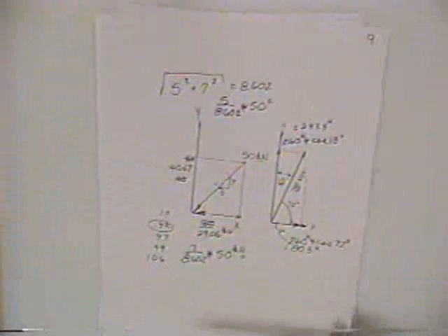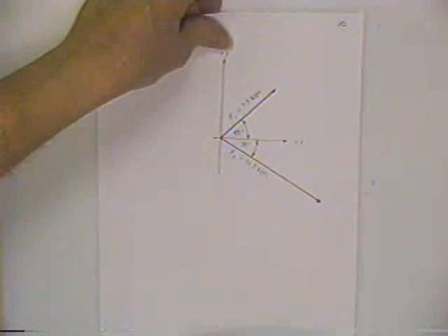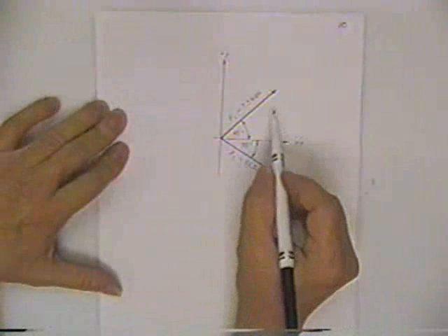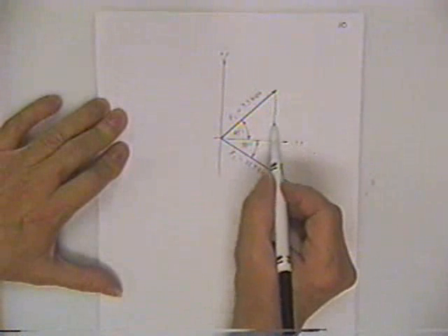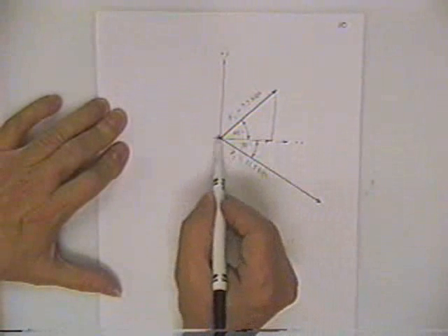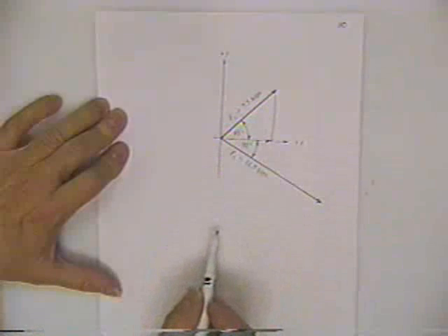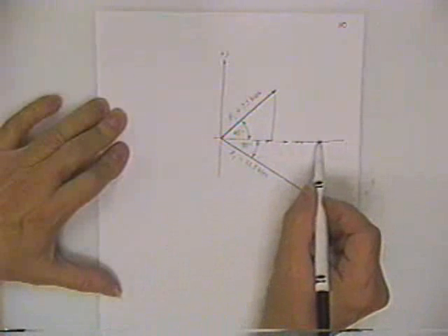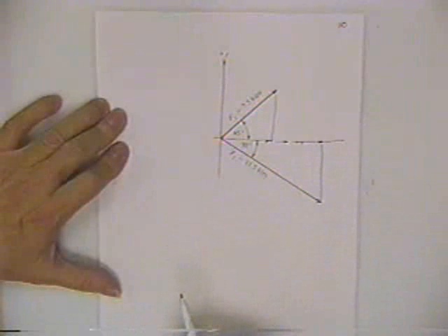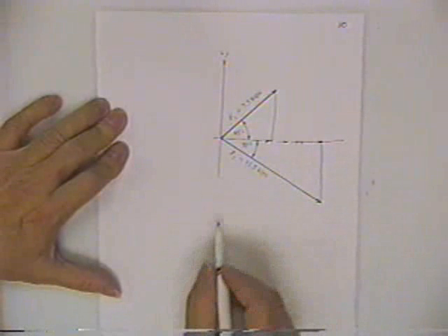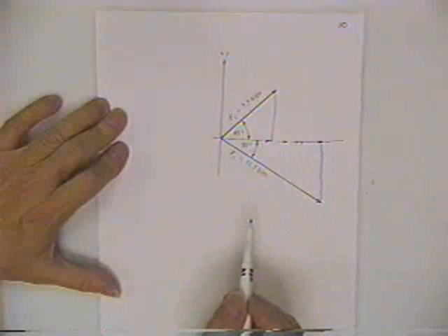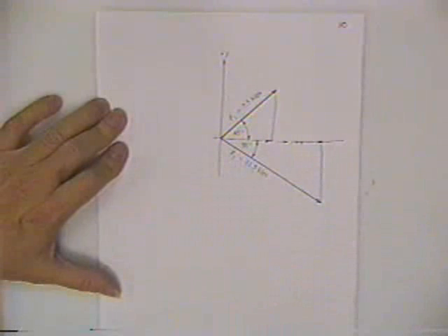Now, sometimes you will be given a pair of forces, and you will resolve them into one single force. We would do the same thing. We would get the horizontal projection of the 7.5 kip force. We would then find the horizontal projection of the 11.5 kip force. We would add them together for the single force that would act in the horizontal direction and be able to replace these two.